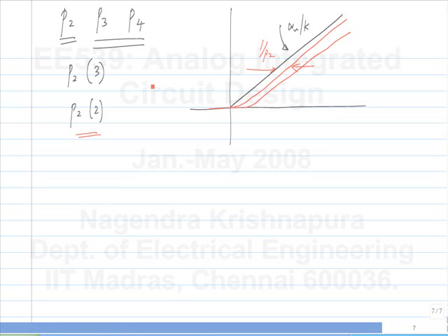If you have multiple poles, in general, you can roughly think of it as each pole adding a delay of its own time constant, that is the reciprocal of the pole. Now I can represent all of this by an equivalent single pole. So I add up all the time constants corresponding to the poles, and I say that it's one pole with that time constant. Obviously this is in error. This is not the correct answer, but it gives me a reasonable idea of what is going on.